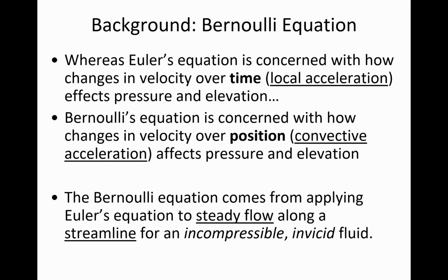And so Bernoulli's equation is trying to predict how a pressure change arises when there's a difference in velocity between 2 points, but it's complicated. If the fluid that you're applying it to can be compressed, then Bernoulli's equation may have some errors. In other words, if you're applying Bernoulli's equation to water, then you're fine for this incompressible assumption, because water is essentially incompressible. We need absolutely huge pressures for it to begin to compress even a little bit. So its compressibility is kind of irrelevant in the context of Bernoulli's equation.